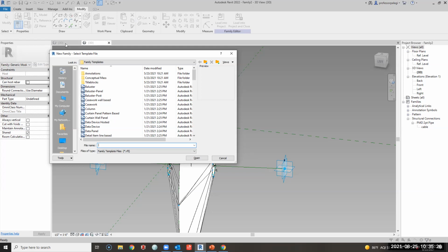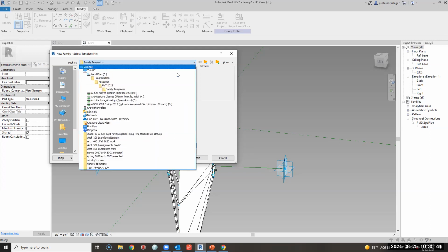If you go file, new, family, you probably get this whole structure of different countries listed and units, right? What I did is I traced back. I went, hey, I don't like dealing with that. So I had this open, I traced back where it was, I went into this file folder and deleted everything else and put this right where it looks. That way I didn't have to deal with any of the rest, and every time I hit it, it opens right there. I made it easier for myself, because you open it like 18 times, and I wanted to save that time, right? It was nothing more than going in and deleting those files in that program manager. That's how I found it, okay?